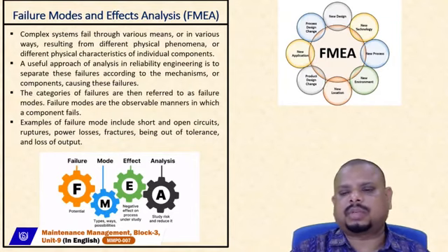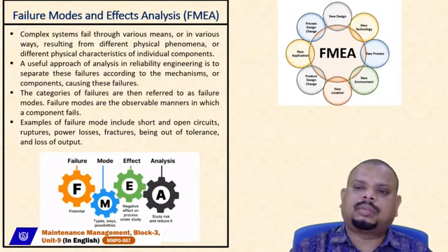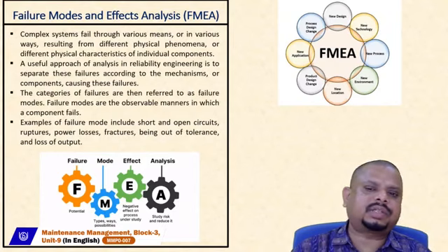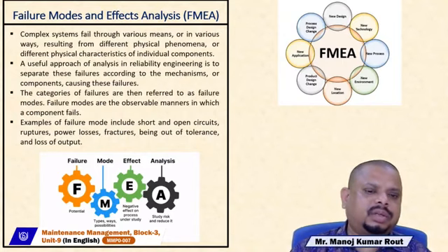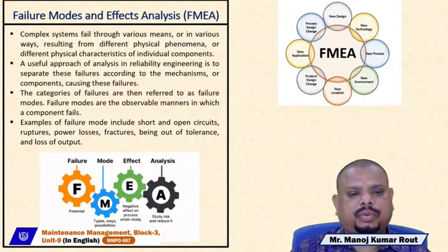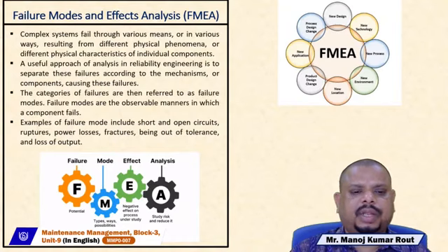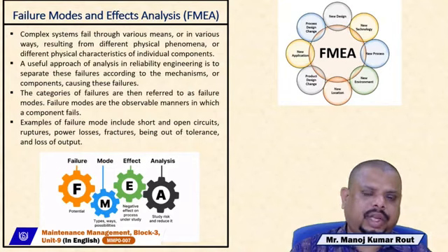So this is the fundamental aspect of failure mode effect analysis and how it should be applied to different areas. For example, it is applicable to new design, new technologies, new process, new environment, new locations, product design changes, new applications, and process design changes. If you go for the categories of failures, these refer to failure modes, and failure modes are observed manners in which the components fail. For example, the failure modes include short and open circuits, ruptures, power losses, fractures, being out of tolerance, and loss of outputs. These are different examples of failure mode analysis.